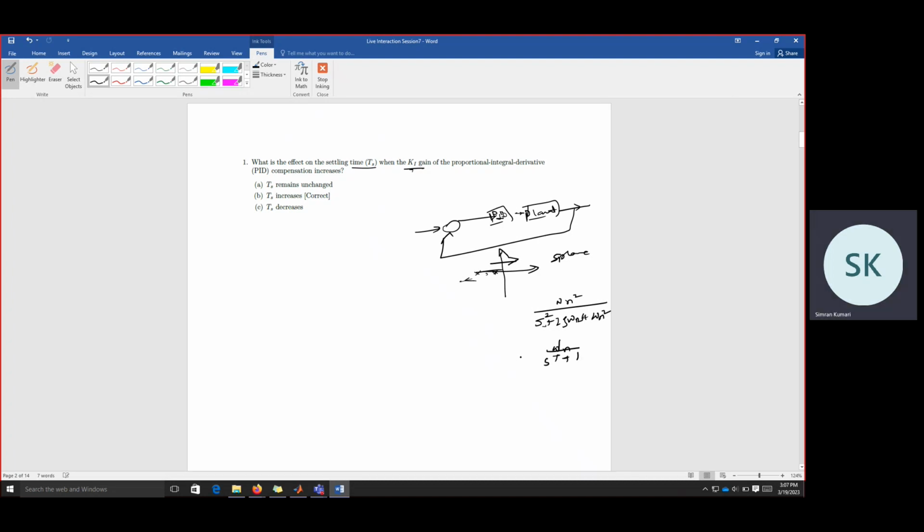So when we are adding this Ki, since it is shifting this way, the location of the pole is shifting rightwards. For a second order system, the root is minus zeta omega n plus or minus j omega n root under 1 minus zeta square, if these are complex conjugate poles.